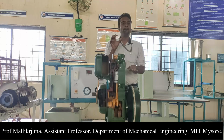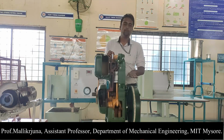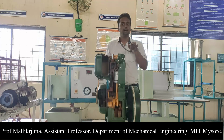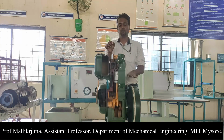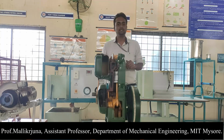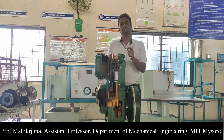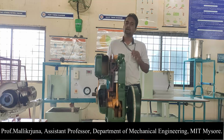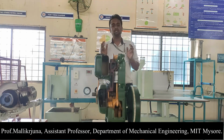Now the compression stroke happens. During the compression stroke, the piston moves from BDC to TDC. Next, the power stroke has to happen. During the power stroke, both the valves are closed and the piston moves from TDC to BDC. Then the exhaust stroke has to happen. During the exhaust stroke, the exhaust valve is opened and the inlet valve is closed, and the piston moves from BDC to TDC. So this is what we theoretically say, and this is the piston's position during the various strokes of the engine.